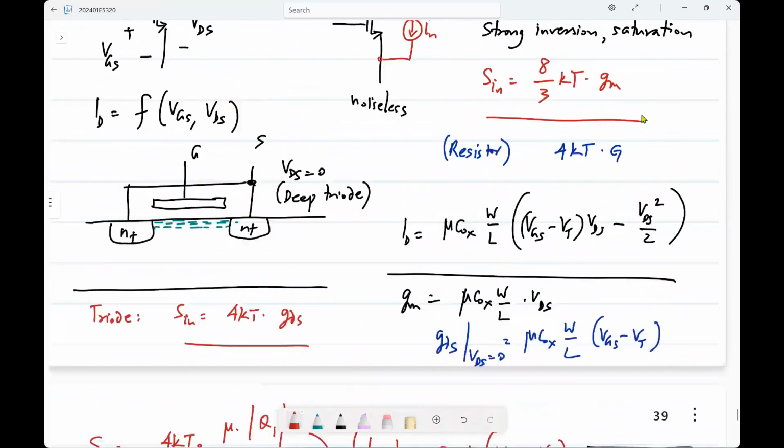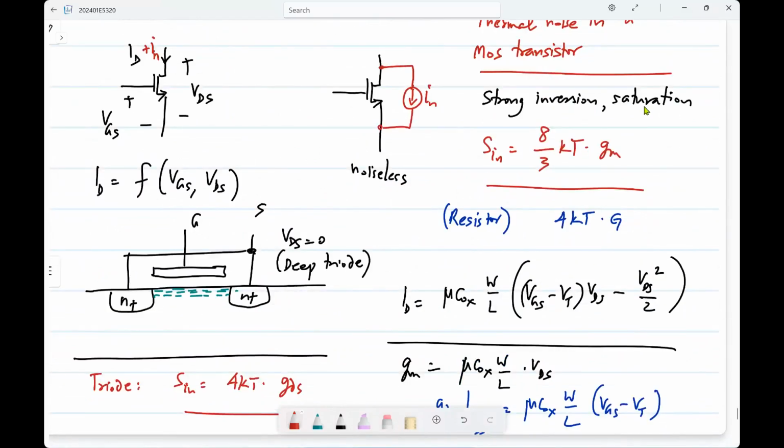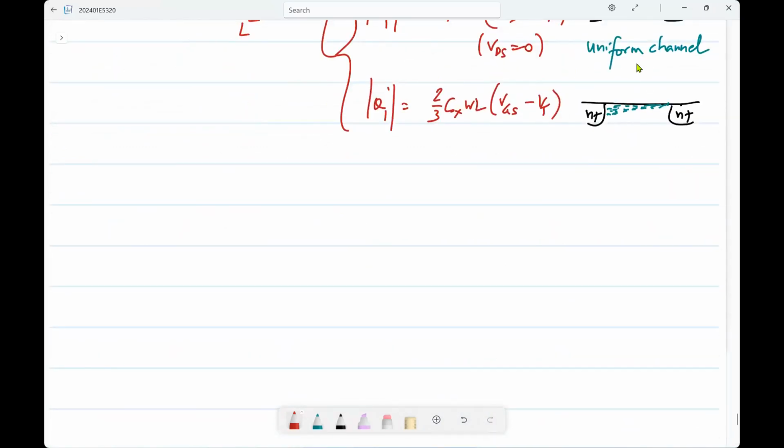So this is about thermal noise in a MOS transistor. This is also white, which means uncorrelated between different instants of time, and all the calculations are exactly the same. You can see mismatch we also modeled by an additional current source. So as usual, in almost every case, it turns out that you have two possible models. You have a noise current whose spectral density is 1/3 kTgm. I'll just use the saturation region expression.